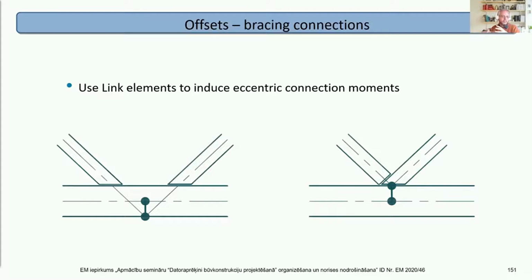When you're modeling the beam elements for continuity, you can then calculate the actual additional bending moments that will occur in those elements. Or you can say, well, it will go plastic and yield, and that's also fine, as long as you are explicitly designing for that.